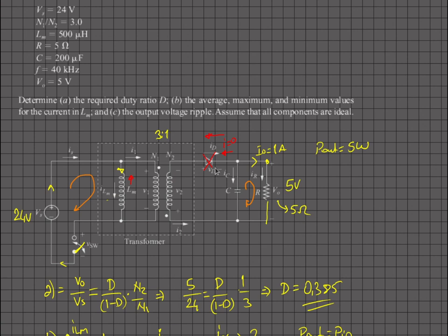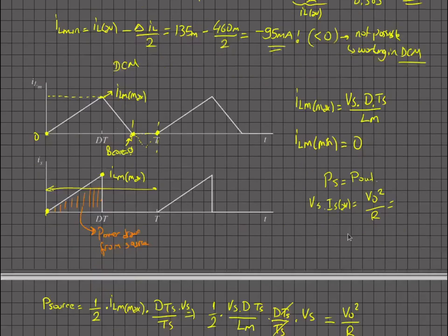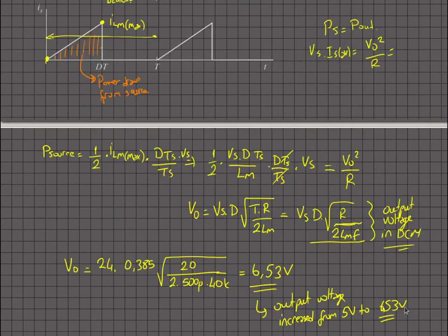That is also why, especially in small flyback converters, the DCM can be a good thing, and at the end of the day it will result in a higher efficiency. There are controllers that can automatically switch from DCM to CCM depending on the operating conditions, because depending on your voltages and current levels, the load current or the load resistance is not under your control, so you need to compensate for that voltage transfer change. The ratio changes, so you need some kind of closed control loop.